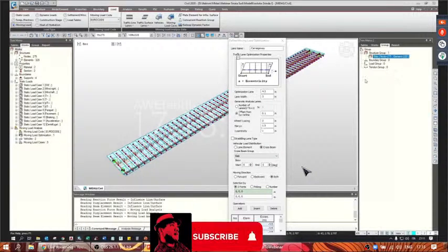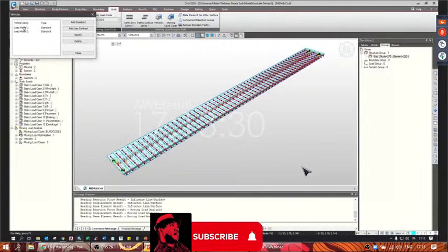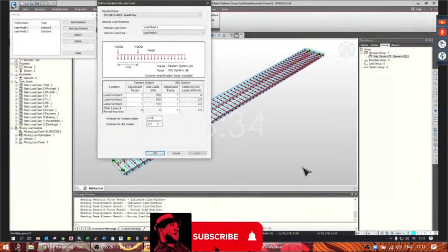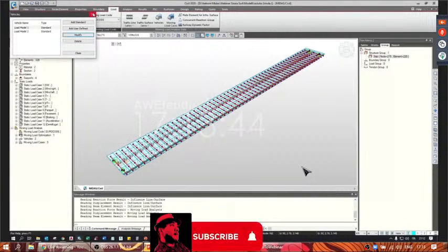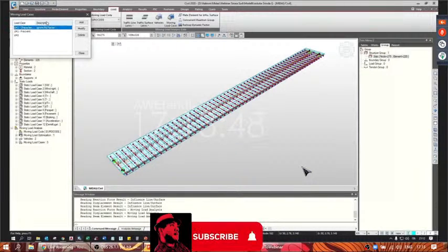Then the vehicles considered are those defined by the Eurocodes, and here we can see also the C factors, that are useful to apply frequent values for frequent combination of load model 1, and we define the moving load cases.